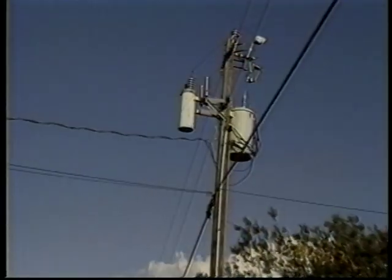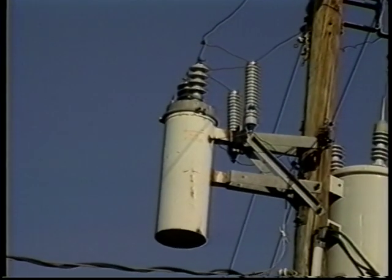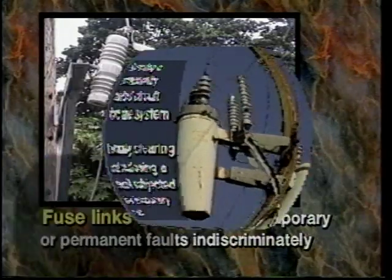Purpose: reclosers are installed to provide maximum continuity of service to distribution loads simply and economically. This is done by removing a permanently faulted circuit from the system or by instantly clearing and reclosing a circuit subjected to a temporary fault.